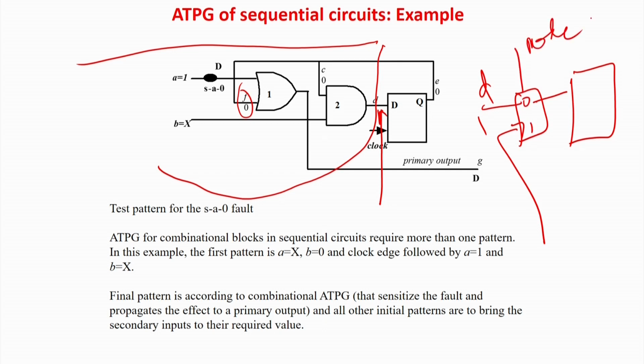So if you make the mode of test as 0, the D will go as the input to the flop, and if you make mode of test equal to 1, the output value you can put in and directly control the flip flop. Anyway, this is fine. You will require a lot of pinouts. This story will remain the same, like a set reset problem. But that is what is required.